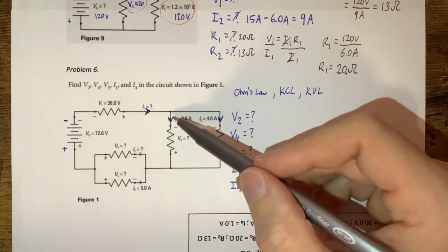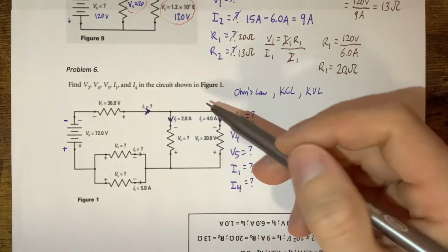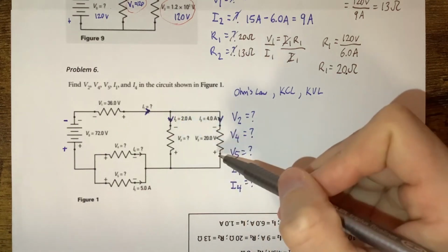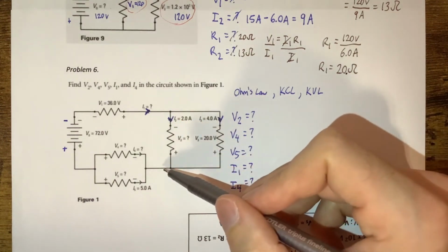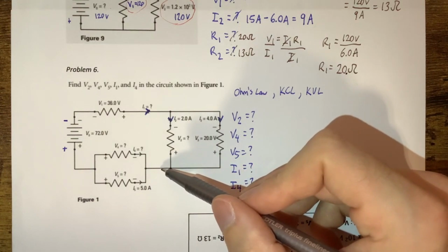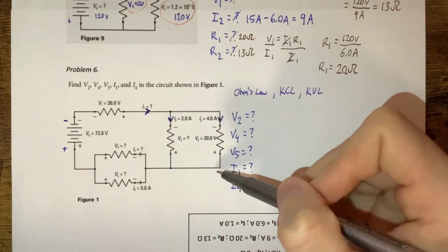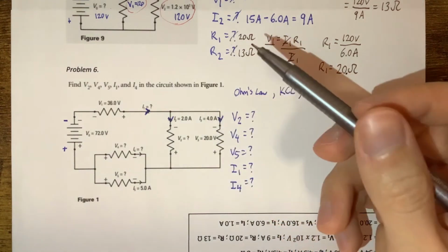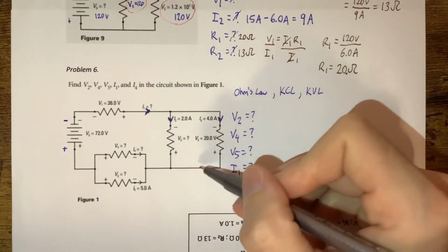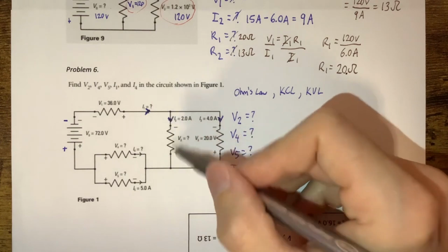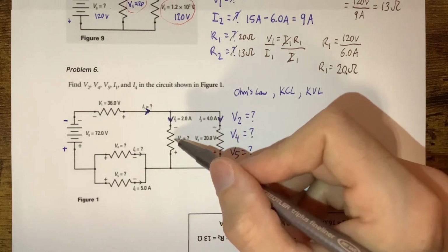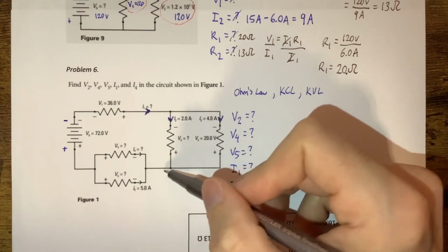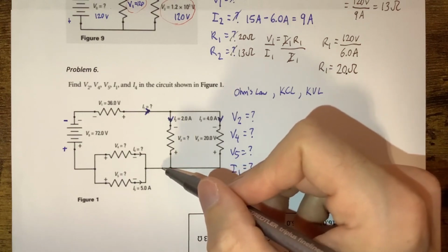And we're going to go down these water slides and we're going down 20 floors each, right? And we're going to be left at the 16th floor, right? So after we go down this one, those electrons have essentially taken 36 minus 20, so we'd be left at 16. You go down here, you're going to lose 20 there as well, so you're left at 16. So all the electrons down here are at 16 volts.